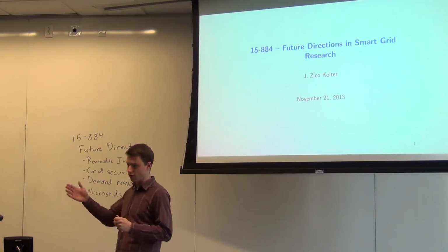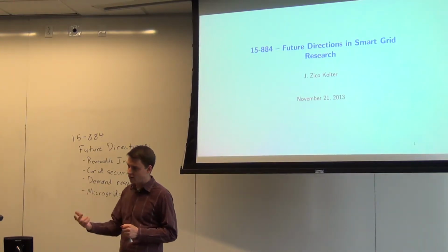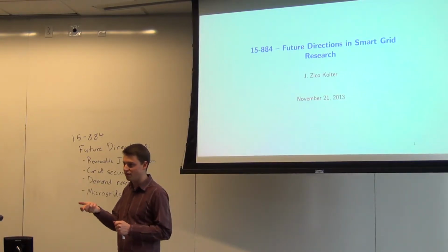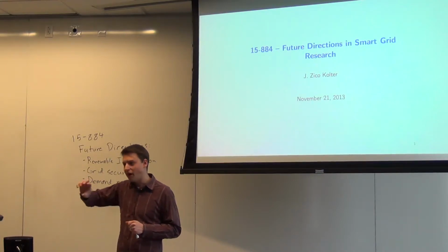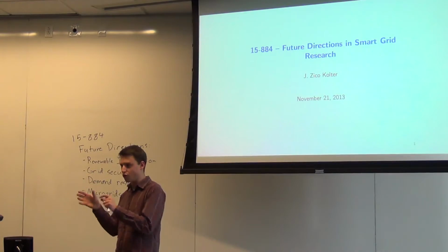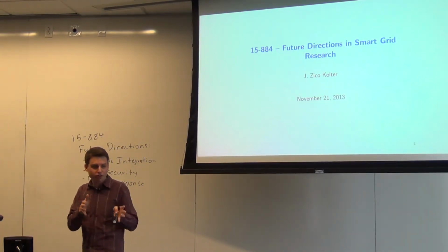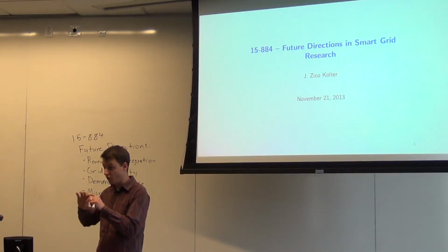The thing is that you don't actually have to worry about what it is for our sake. I mean, you can, but all that matters is omega minus omega ref. So basically what matters is your deviation from the true value. So if you set up your set of equations such that your state variable is omega minus omega ref, then you don't have to worry about it at all.